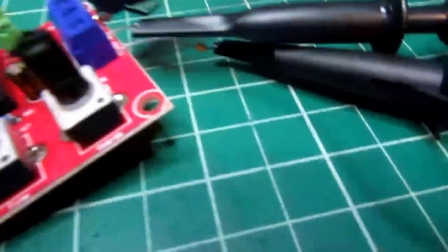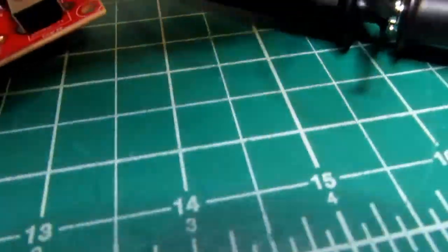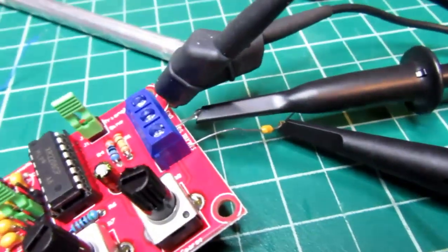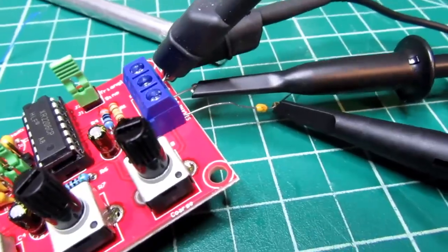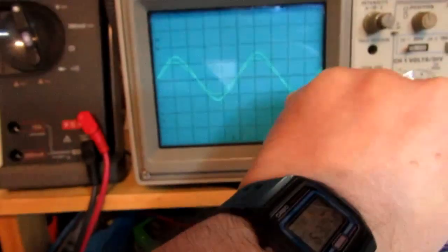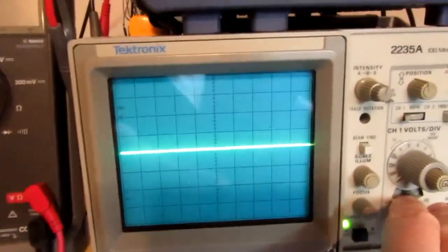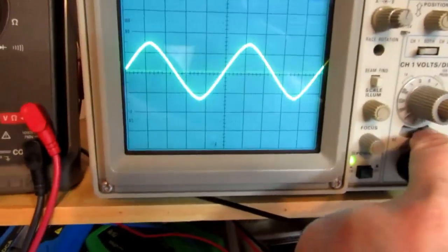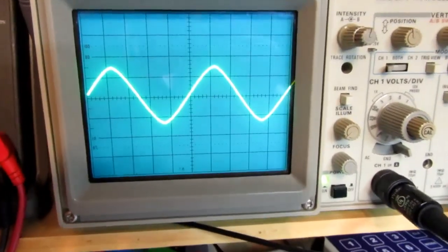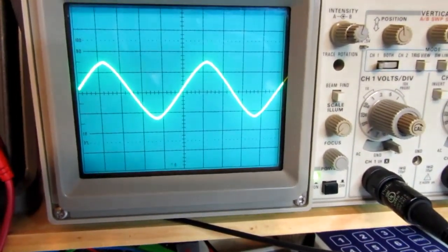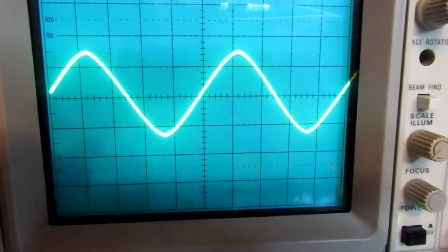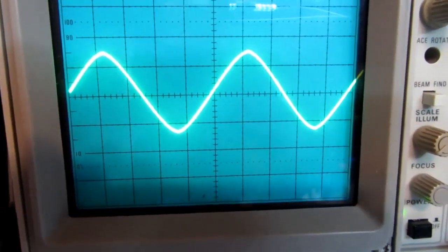And I'm using a 0.1 microfarad coupling capacitor coming out of the sine wave, triangle wave output. So now I've got 0 volts there, and the output is centered plus and minus around it. We still have this really pointy pseudo sine wave.